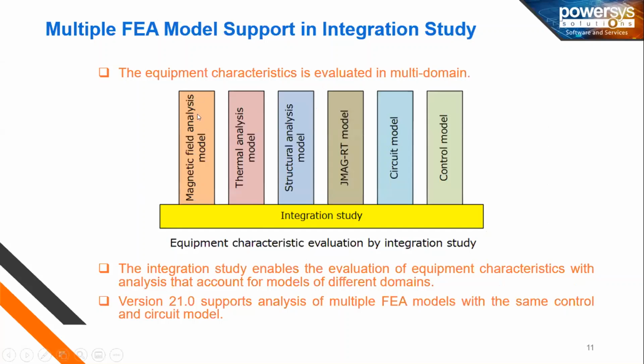And this is the new feature added in version 21, which is multiple FEM model support study. We have known that with the help of integration study, we can perform studies from multiple domains, like the magnetic field, the thermal domain, the structural domain, or from the RT model or circuit model. Whatever it may be, everything gets integrated and we can perform the study. And here in this new version, this is how we are going to apply multiple FEM models with the help of the integration study.